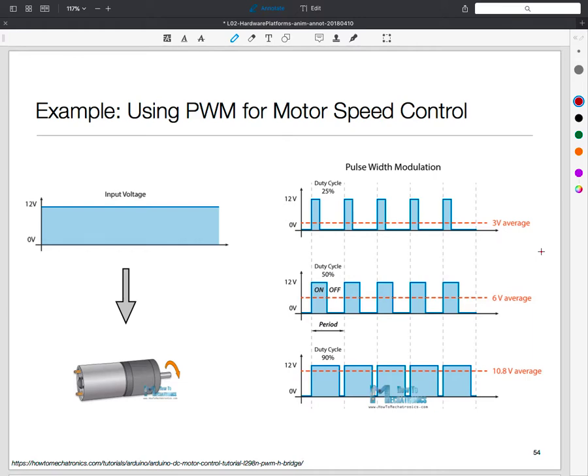It turns out that this way of talking to motors to control their speed, or even to control their position, in the case of motors where the position is controllable, has become very common. You can buy so-called servo motors for robotics and all, which take a PWM signal. So you just need to supply a PWM signal, and the motor comes with the circuitry to handle the rest of the stuff. They are often called electronic speed controllers. So, motor plus a little circuitry. If you are into remote control cars or drones and stuff like that, you'll find that the motors used in them basically come with these kinds of controllers, and they take a PWM signal.